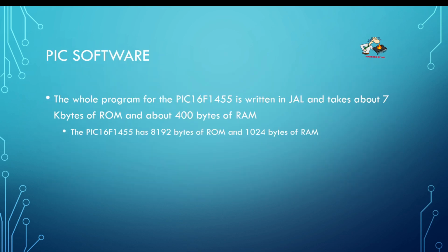So the PIC software, it's about 7K in ROM size and 400 bytes of RAM, and the PIC that I'm using is the 16F1455, which has USB capabilities. And the PIC itself has 8 kilobytes of ROM and 1 kilobyte of RAM.